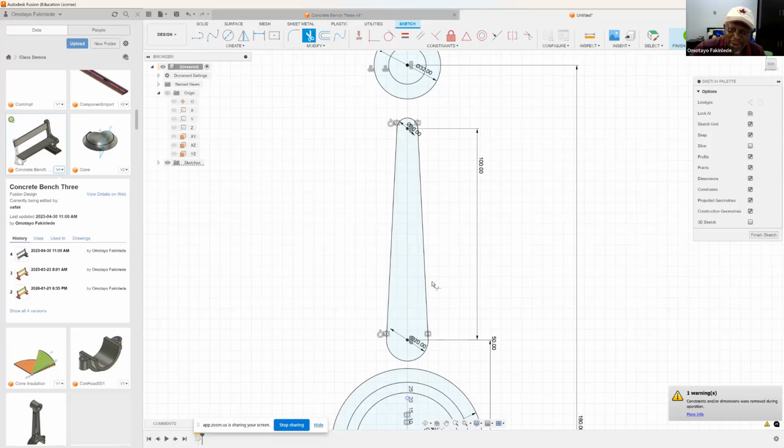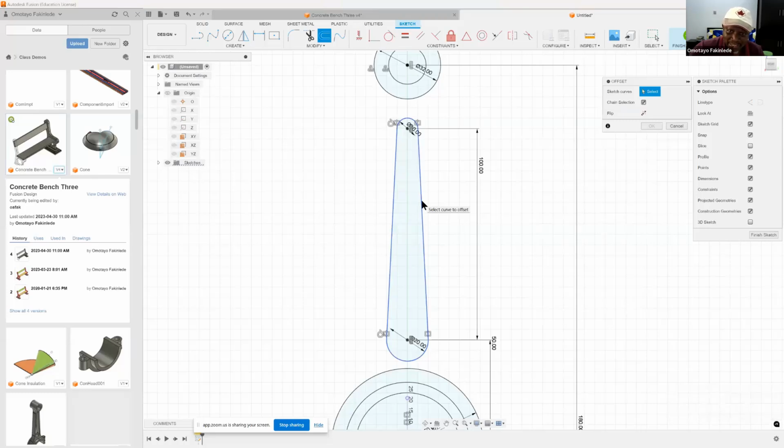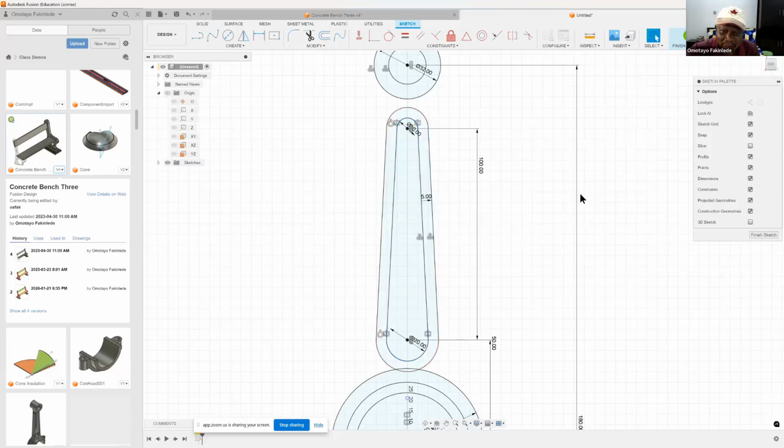I'm going to do an offset of this whole path. I will do it out by 5 millimeters. So I can create an offset. And this whole part is a single part now. I want to offset this. I can offset it inside, I can offset it outside, or I can select the particular amount of offset I want here, because it is taking the outside as minus. So I'm going to offset it by -5. There. That gives me an offset here.